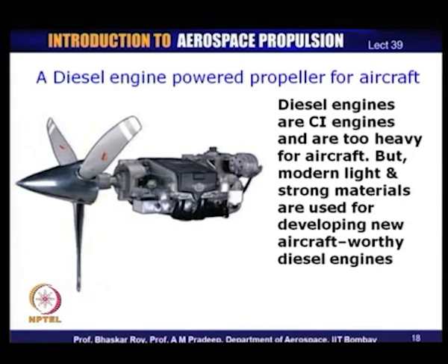Now, if this is technologically possible, CI engines would provide better fuel efficiency, and that is always sought after in aircraft applications, because you then need to carry less fuel with you. This is one kind of engine that is being developed, and if the new materials, the new alloys, the titanium alloys or the various kinds of aluminum alloys, are strong enough to withstand the high pressure inside a CI engine, they become a very good candidate for application in aircraft, and the thrust to be created by the propeller.